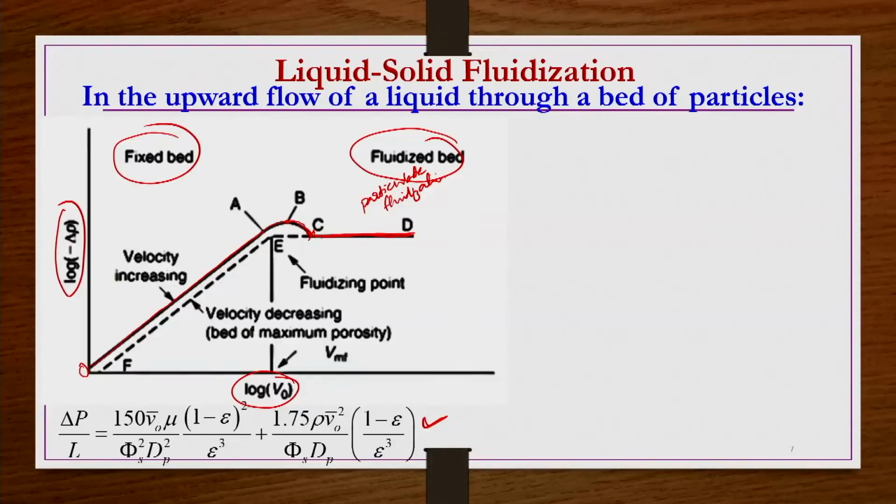Right. So, when you attain the particulate fluidization conditions, and you find that the pressure drop is independent of the velocity, then you decrease the velocity again, gradually. When you decrease it, the curve goes from C back to D, and from C it is not going to follow the BA path, rather it will gradually decrease further.